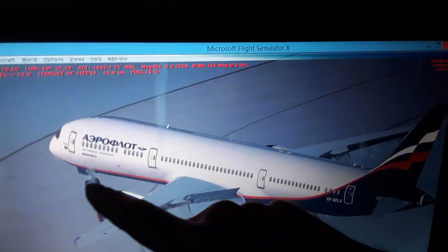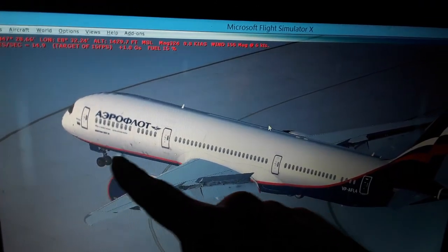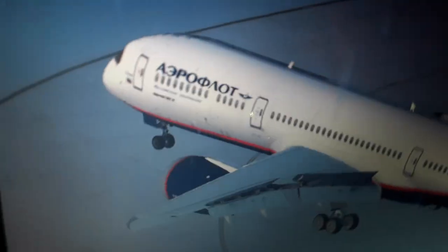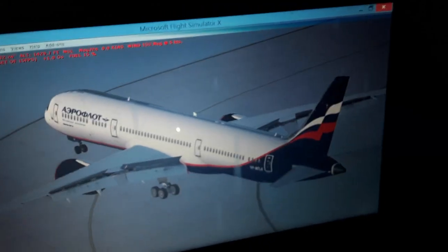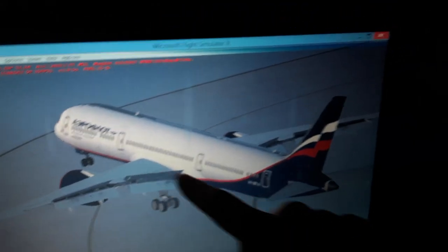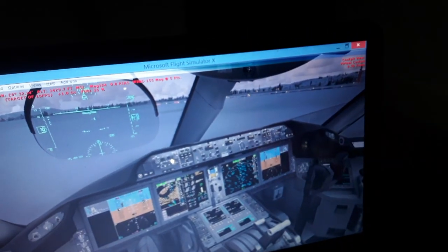So the computer will decrease the deflection above 45 knots or 72 kilometers an hour, from 76 degrees down to 7.6 degrees deflection, either left or right, for the forward nose wheel like in takeoff or after landing. So as we accelerate even further, you don't need to do anything, only press the rudder pedals in takeoff or in landing.